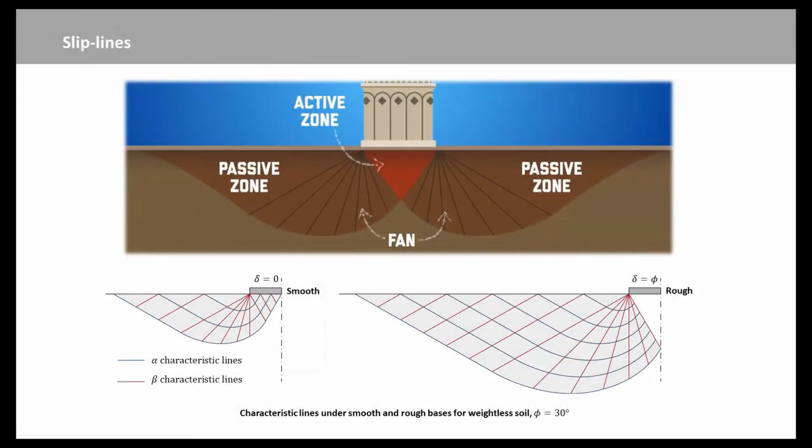Impending plastic flow of the soil occurs when a sufficiently large region of the soil beneath the footing is stressed to its limiting or yield condition, resulting in an unrestricted plastic flow of the soil beneath the footing. At the instant of impending plastic flow, both equilibrium and yield conditions are satisfied in the region near the footing. For soils, the Coulomb criterion is widely used for this yield condition.